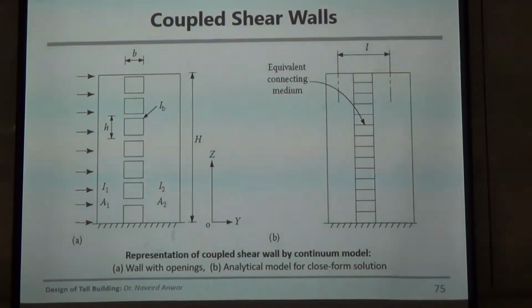Number one. Secondly, we can control the ductility through those link beams by putting hinges there. So like I mentioned, both stiffness and hinging, both properties that we desperately need in a tall building, can be provided by linking frames and walls or linking walls and walls.